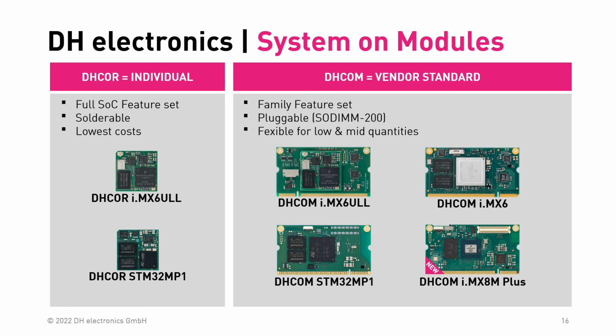Here I would also like to mention that the SODIMM was developed for portable computers like laptops. Therefore, the connector fits perfectly for products which have higher shock and vibration requirements. Next to this, it is a cheap connector. So please think here of the hidden cost topic from before. A cheap connector is always good.